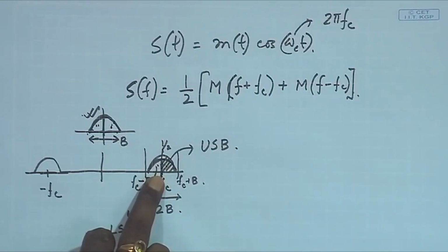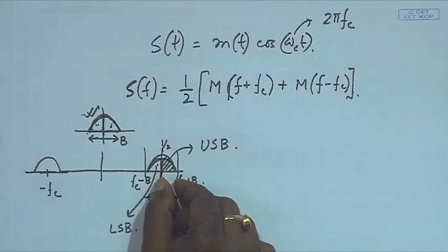So if you just do this modulation, suppose for the same band you can transmit n simultaneous communications. If I could reduce this to half, I could transmit twice that number. That is a big number. Suppose I can transmit 6 radio channels over a band, now I can transmit 12 radio channels within that same band. So cost-wise that will be much more effective. We will definitely target that, but right now we should be content with this modulation.